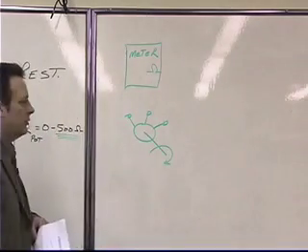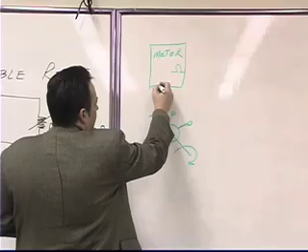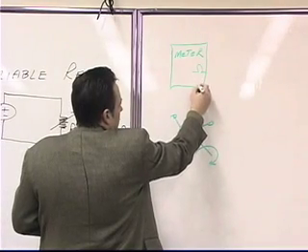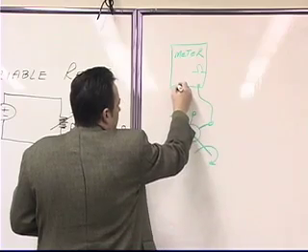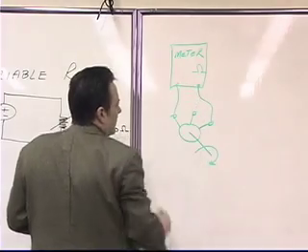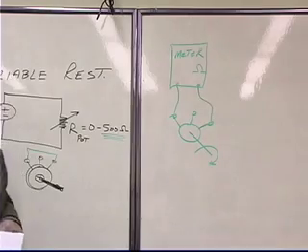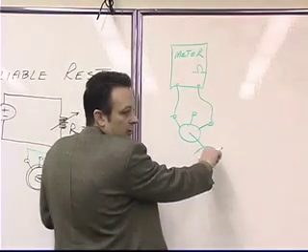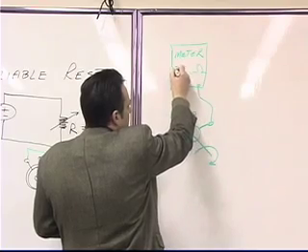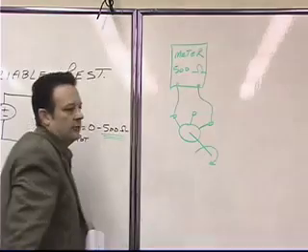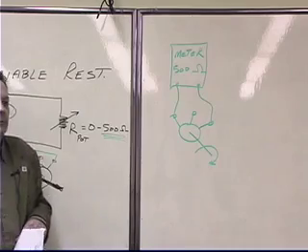So your meter is measuring ohms. And then you take one lead from your meter and you connect it here, and you take the other lead from your meter and you connect it here. And you turn the knob, the value of ohms will not change. It will be its maximum.